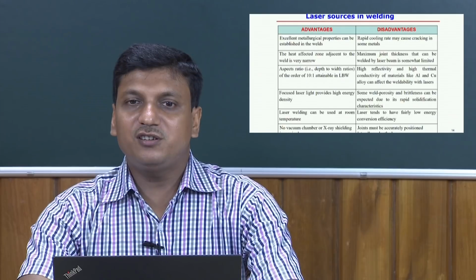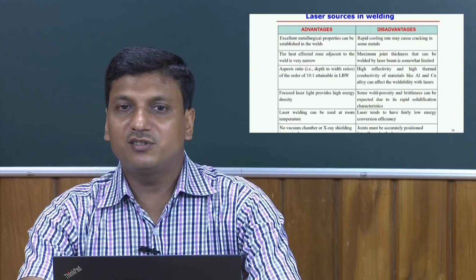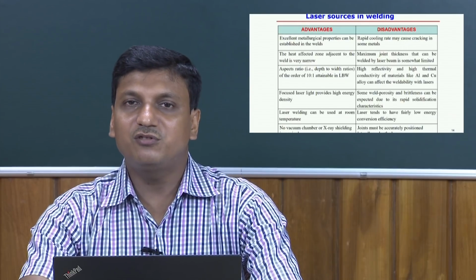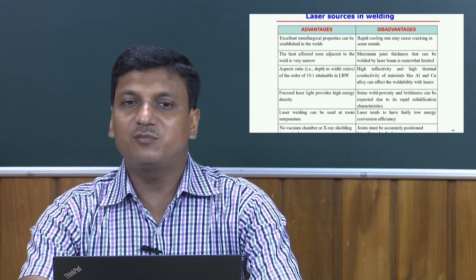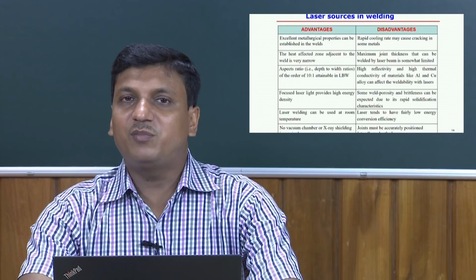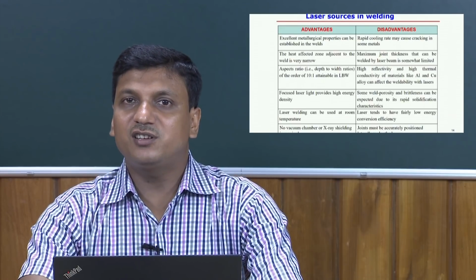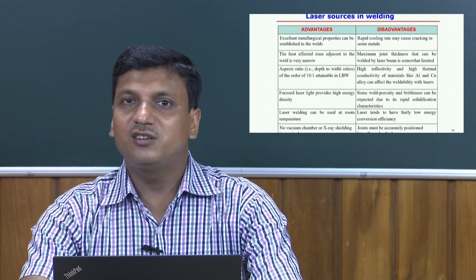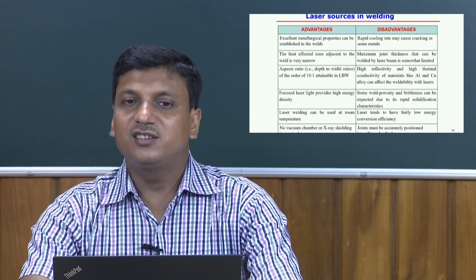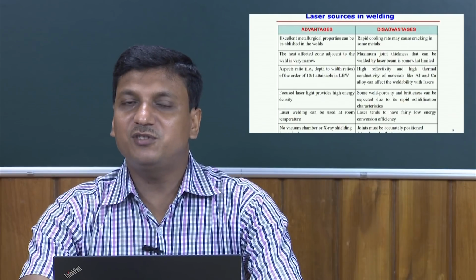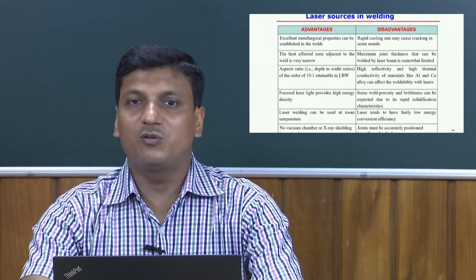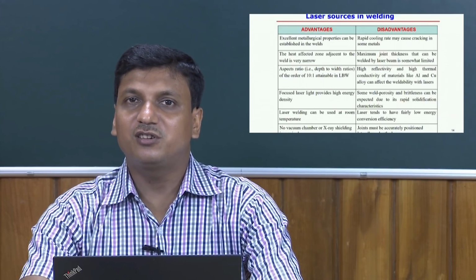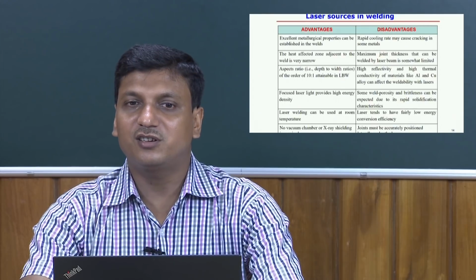Some weld porosity and brittleness can also occur due to rapid solidification, which is another disadvantage of the laser welding process. But the main disadvantage is that, for the normally used CO2 laser or Nd:YAG laser, the process energy efficiency or energy conversion efficiency is relatively very low, maybe around 30% or less.